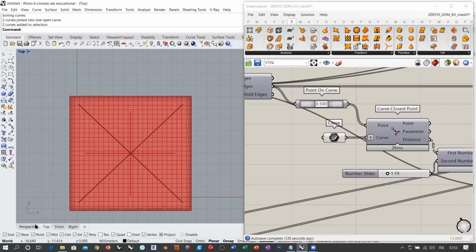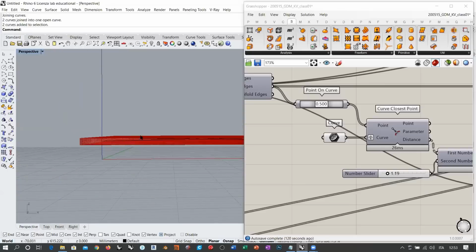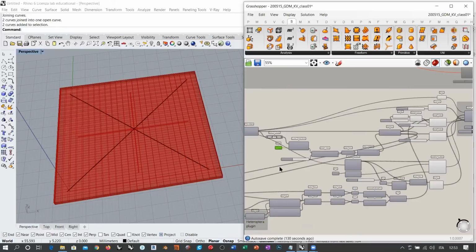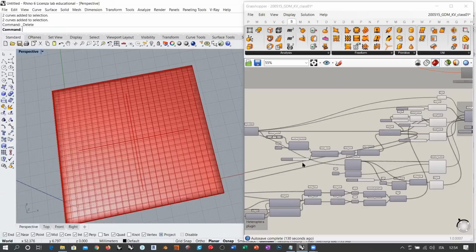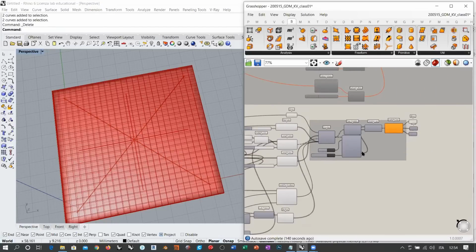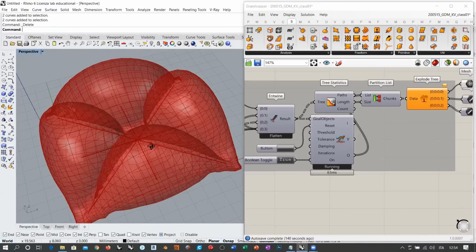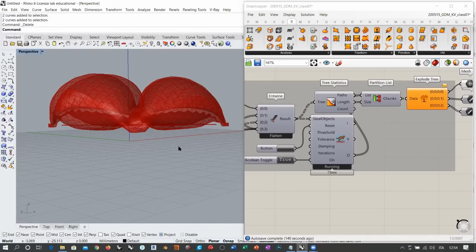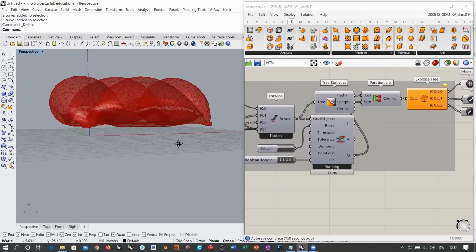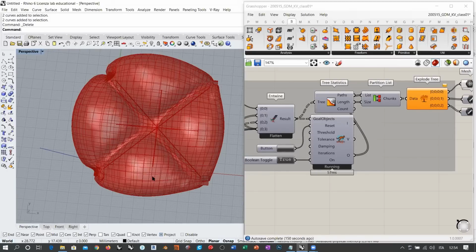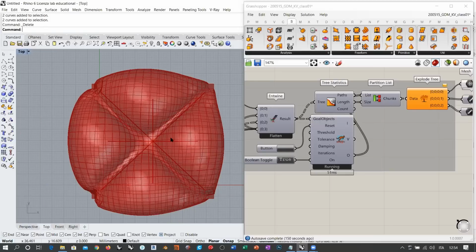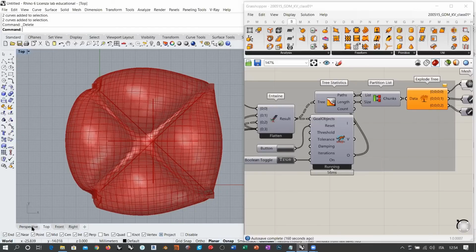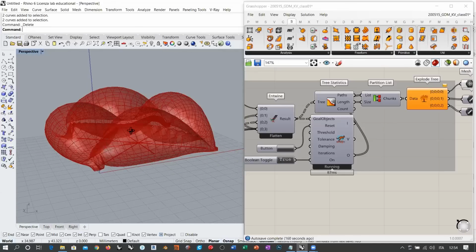Now this is way more precise than before. It lies always at mid height. So let me internalize this data so I can get rid of these lines, which by the way are still there. And now everything should be more controlled. You see that now we get a more symmetrical behavior. And so this thing is going to increase its height, and the symmetrical behavior also depends on the mesh topology. You see that in this case, for example, there is some shifting to the left. Now the problem with this is that it also depends on the elastic property.